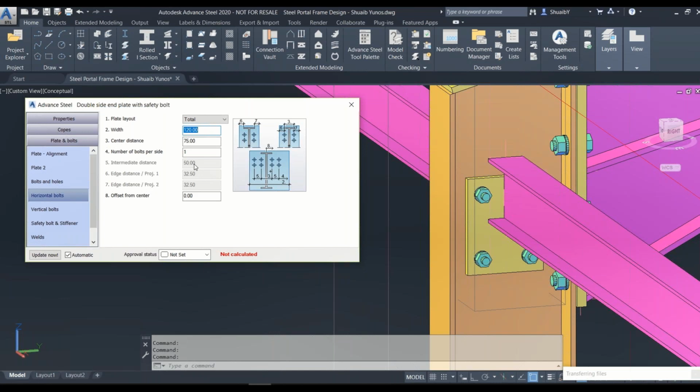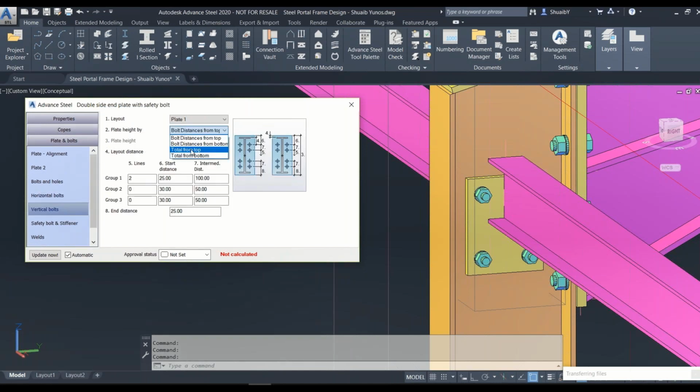Here it looks fine. And then you can see here there's no middle, right? For some reason, because it's a double plate. So we're going to use, let's choose one, right? Let's say top, okay. Right, so what's the problem here? Why is it not snapping to the top? Very simple, you can see the layout distance got an offset of -30. Let's go and change that. All right, so if you make that 0, it snaps to the top. So don't get freaked out if you don't see that. It's just the input parameters that you need to pay attention to, right?